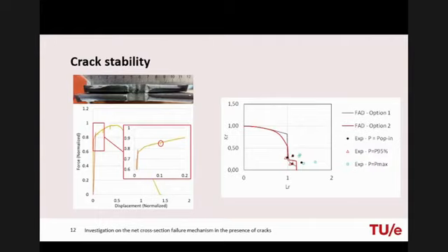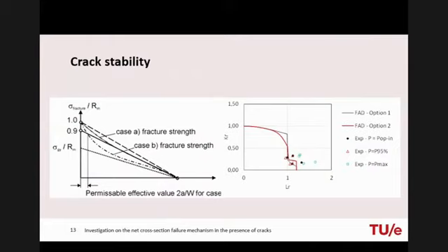In particular, for the brittle fracture ratio Kr, we considered the corrected value for the fracture toughness, higher than the plane strain fracture toughness calculated using the master curve approach, considering beneficial effects of the negative T-stresses. In any case, the location of the assessment points in the failure assessment diagram confirmed that the dominant failure mechanism is ductile failure. For this reason, we think that this steel is case A as reported in the commentary to Eurocode 3, since the fracture toughness is relatively high for low strength structural steels.